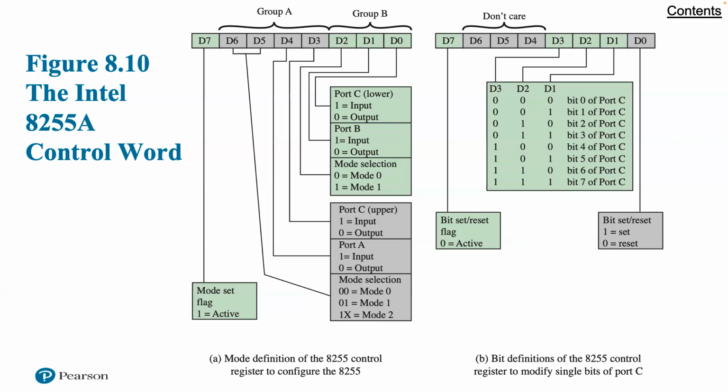for A and B. The control signals serve 2 principal purposes: handshaking, and interrupt requests. Handshaking is a simple timing mechanism. One control line is used by a sender as a data ready line to indicate when the data are present on the IO data lines, and another line is used by the receiver as acknowledge, indicating that the data has been read and the data lines may be cleared. Another line may be designated as an interrupt request line and tied back to the system bus.